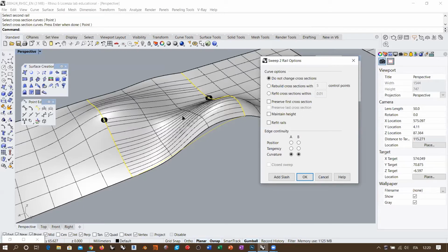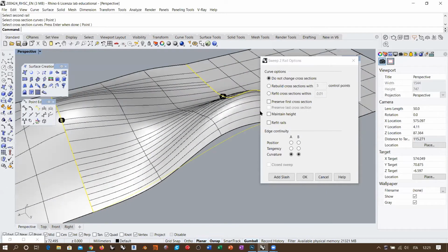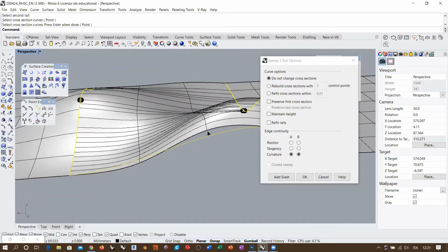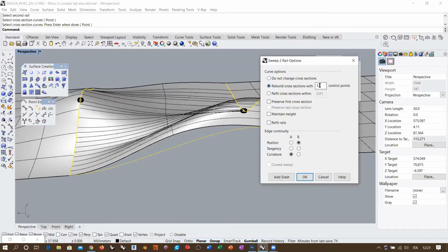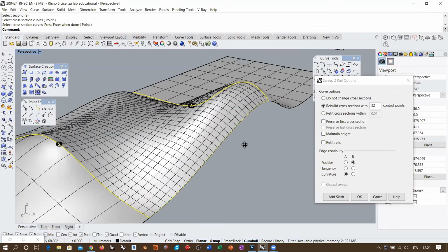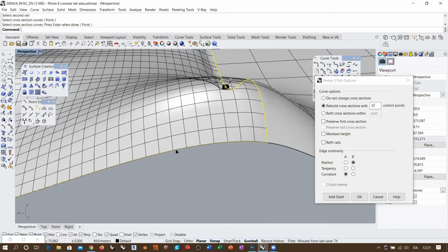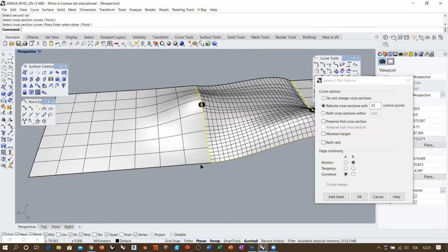The other thing that you can do eventually in this case is use the proper topology, like 6 control points degree 3, but at the same time rebuild the cross section with, I don't know, more control points. Now, if you do this, you are saying basically that your cross section has become more and more complex, okay? Yet this cross section, which in this case adheres to the original shape, is not curvature continuous with this surface, not even with this surface, okay?